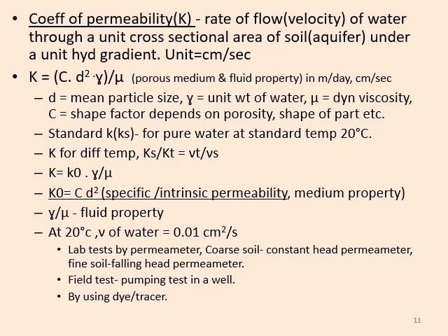So if we equate K with the porous media, d square, and fluid property, we will get a constant C. C is known as shape factor, and it depends on the porosity and shape of particle.